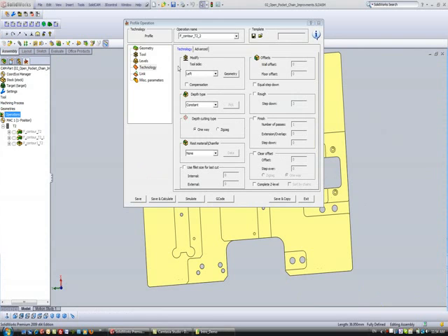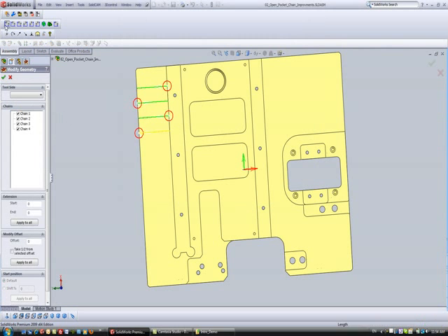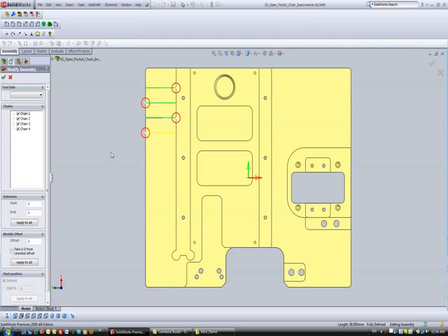Now if we go into our modify geometry area, first of all I want to choose to work on the center. Now when I click on geometry, you'll see my tool is actually going on the center of the toolpath. Now I'd actually like to move that over to be in between these tool paths. So when I go into modify offset, we have the option here of take half of selected offset. If I click now on this line over here, I'll get the automatic halfway point between that offset over there, going exactly in between those two chains.